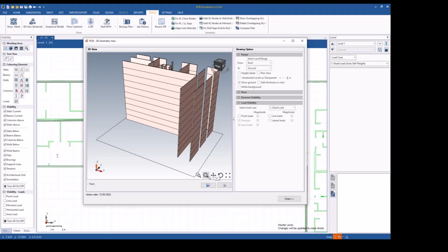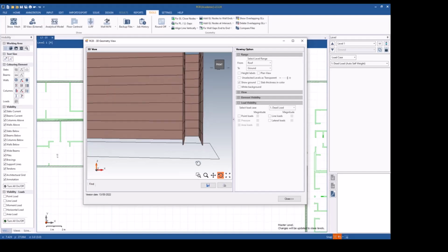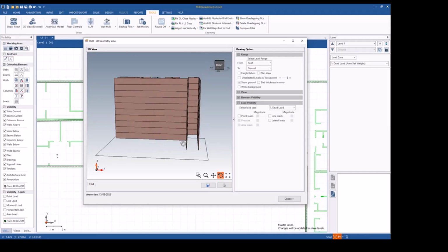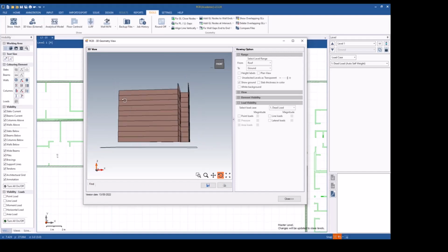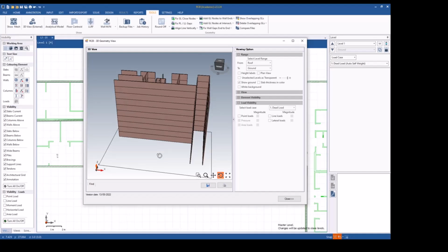Now, what we can see here is the vertical elements. You can see at the ground floor, we don't have anything. We will copy it later. We will copy the columns, the walls, and that one column to go to the ground floor as well. Why I didn't add it as a slab is because when I draw the slab, it's going to be placed from the roof all the way to the first floor. I don't want to put it for the ground and then delete it, but it's up to you. You can still do it if you wish.